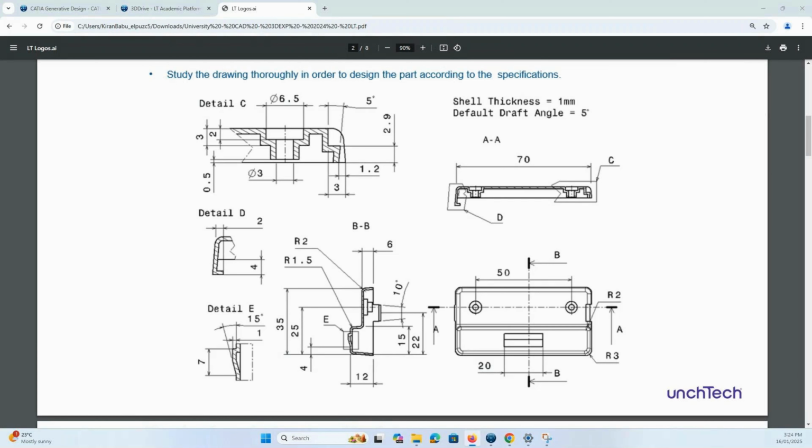When you work on your capstone project, or on projects, you start with a concept, and that's eventually going to change, and you might not have control over it, because it could change because of the physics, because of dimensional clearance, or because it cannot be manufactured in that way, and so on. So there are different reasons for it to change. So I like to keep my model as parametric and as dynamic as possible, so that I can quickly make those changes as well. This means that I start off with the main body, and then I start refining it based on how we'd like to achieve it. Okay.